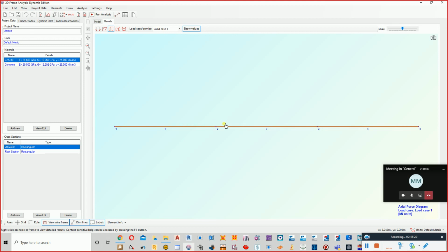For example, when it comes to the beam, this is my major axis and that is going to be my minor axis. The load is acting perpendicular to the major axis. Okay. So beams and slabs are flexural. That's why they are designed for bending. We design them for bending. When it comes to columns, mainly we design them for axial loading or forces. Okay. So shear force diagram, and then we have bending moment diagram, because this was a fixed support and this is ending at zero.